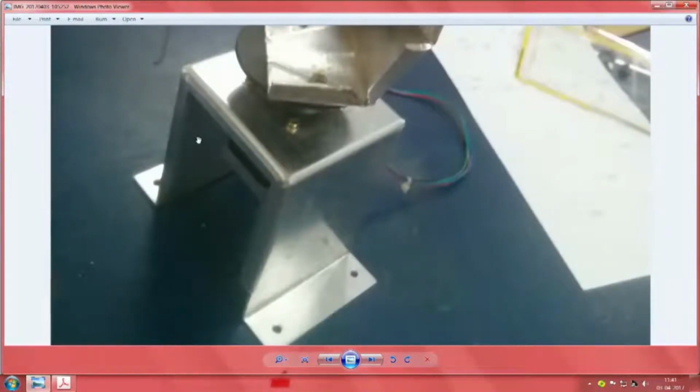In the real piece, you see here on the corners a small cutout, and then this small step here is intended because of the sheet metal machine that we have there. We have a folding machine which has clamping fingers, and then the bottom jaw part of it has a limitation about the depth with which we can go. Hence, this cutout was necessitated when we tried it last time.